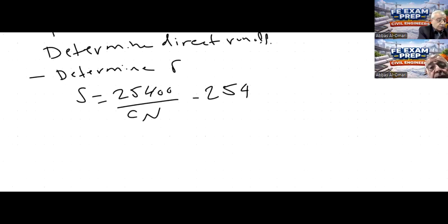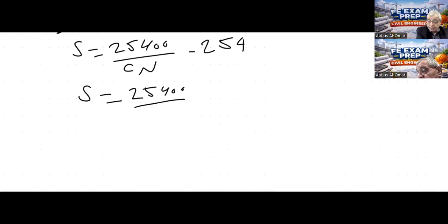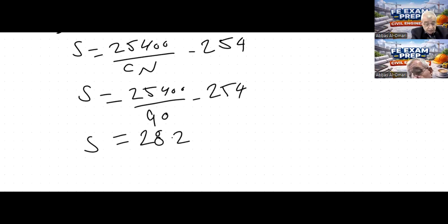So storage equals 25,400 divided by the curve number, which is 90, minus 254. And that gives us storage equals 28.22 millimeter. This is the storage.